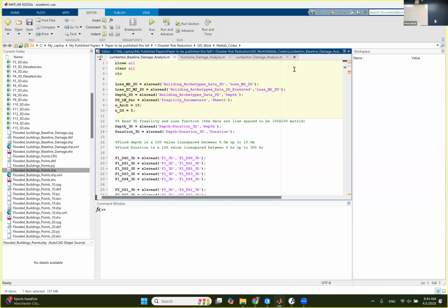So this is the original one, if you have all the components in the same original place. But let's say you elevated the water sensitive components. What do you think? This curve is gonna be down or is gonna be up? Okay, so let's say it's gonna be here. So if I'm having here, let's say, a flood depth of 2 meters, and you go up, this is gonna give you, for example, 15%, but the original one is gonna give you, for example, 35%. So you reduced by 20%.